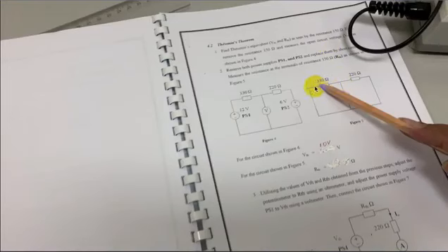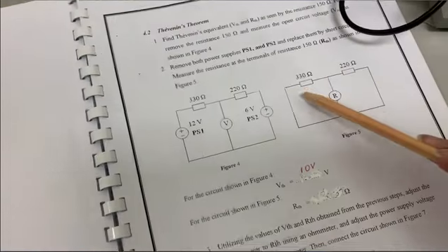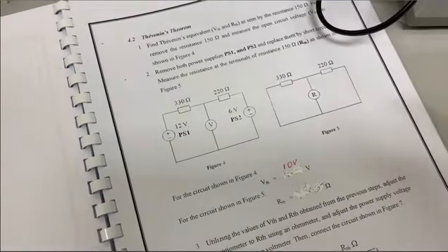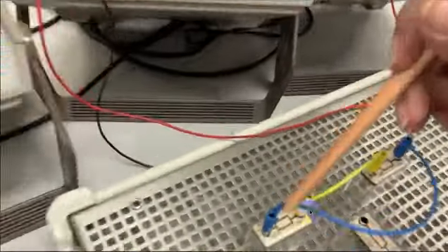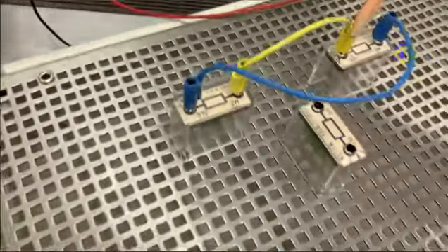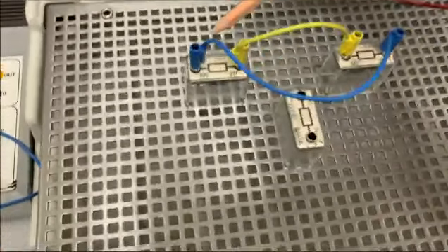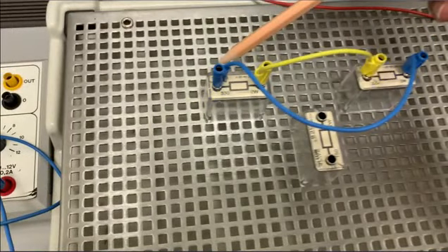I will connect from these two points. These two will be in series, and from these two it will be in series like this. Okay, this point and this point I will connect an ohm meter. So here we can find the total resistance. 220 I have connected like this, and 330 to this point, 220 to this, and 330 in this fashion. It is actually parallel, not series.